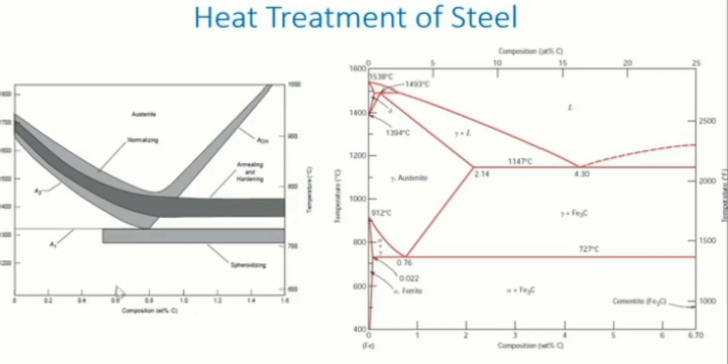So it means this is your phase diagram. I'm just bringing this for you to understand. Already we did this in 309. So it's within this region. Can you see my mouse head? Yes, sir. And remember, the V is the austenite region, isn't it? It means in this case, you will have to heat from the alpha plus cementite till you reach the austenite region. But as you reach the austenite region, this V, it must be 55 degrees above it.